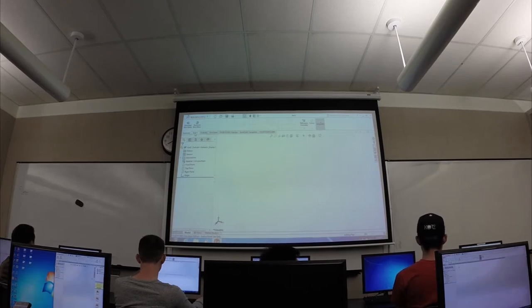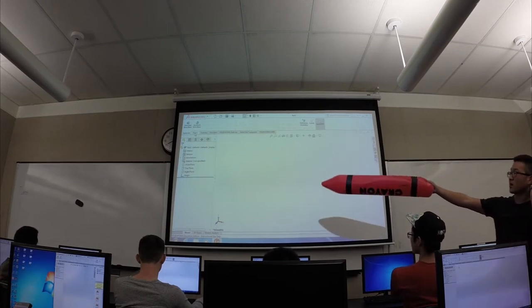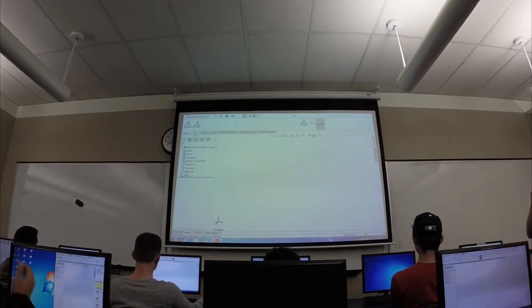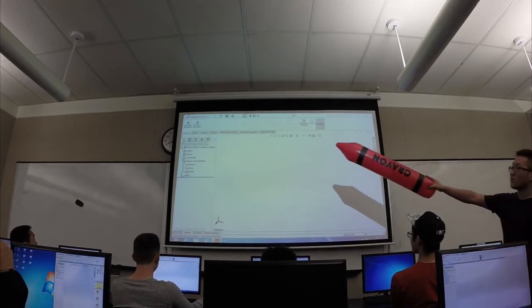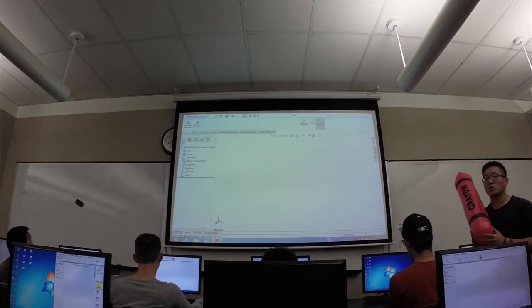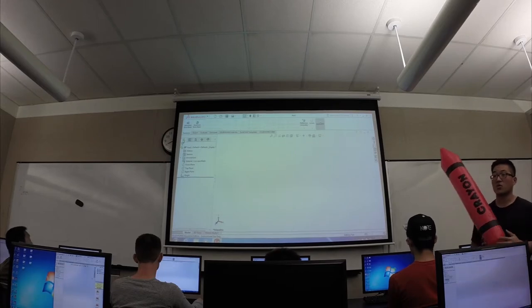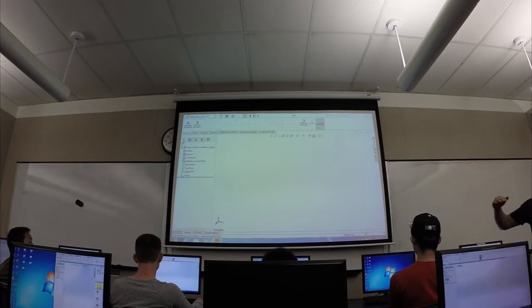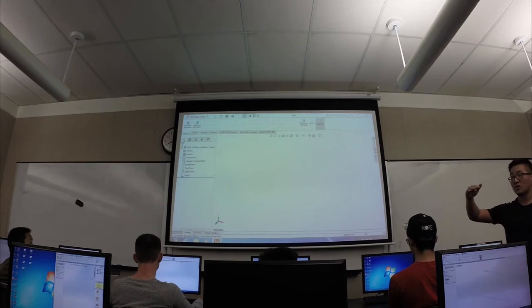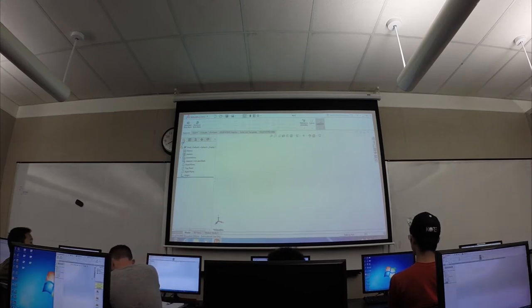Yeah. Okay. So you have that on the toolbar on the top, and then on your left, you have your little tool pane over there. This part is super great. The first tab, this little yellow part image that you have, is called the feature tree. What the feature tree shows you is what kind of steps or operations you have taken on a part. This is great if you want to roll back to a certain feature at a certain time, say, okay, I want to edit this step first. This is the place you would be looking at all these steps.